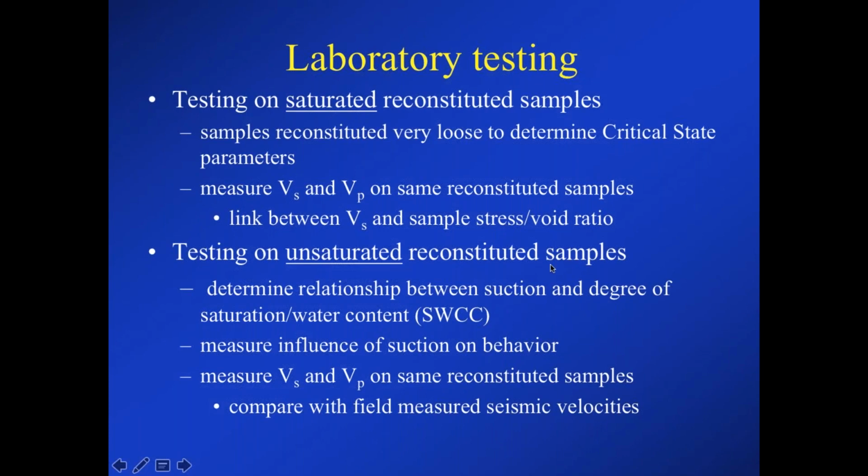And then we also were able to do some tests, and this was really with the help of Antonio, where he had a number of graduate students that actually did some additional tests on unsaturated reconstituted samples. So the same reconstituted material, but we duplicated them, made them very loose, but kept them unsaturated. First we determined the relationship between suction and degree of saturation or water content, the soil water characteristic curve, which I'll talk about briefly.